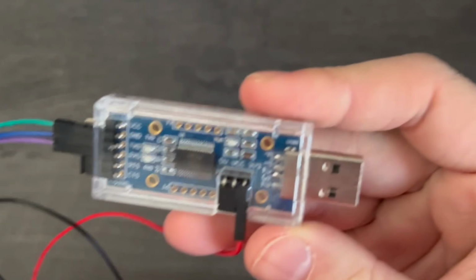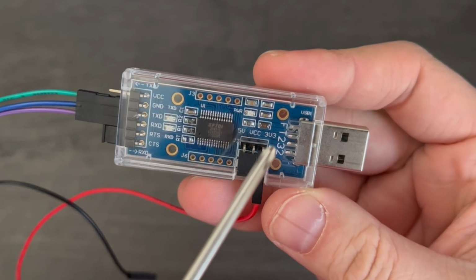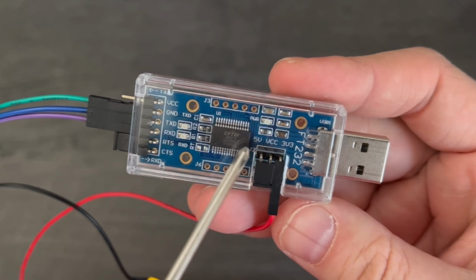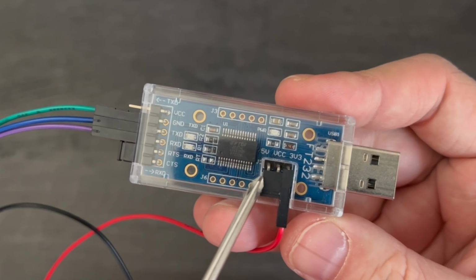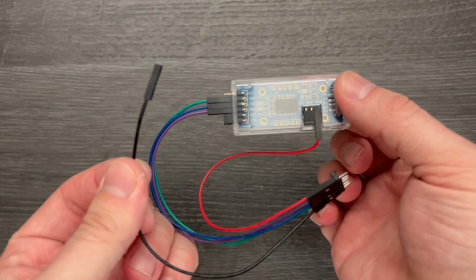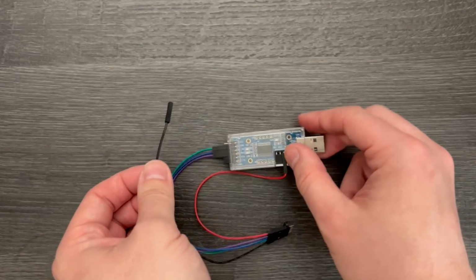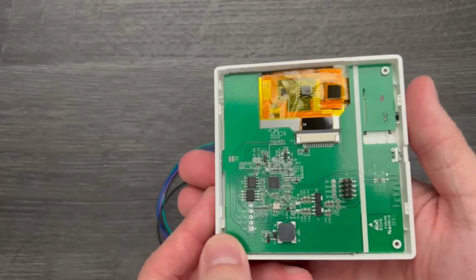If you're also making use of the FT232, then do make sure that you're connecting it to 3 volts and not 5 volts. If you do accidentally connect it to 5 volts and you try and power the panel or flash the panel with that, you can potentially damage it and burn it out, so don't do that. You'll notice that we've got this black wire that isn't connected to our adapter,